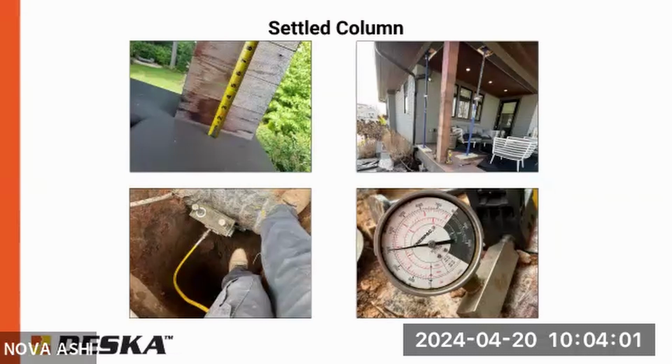And in the ground, there's not a lot of air. If you drive by a bridge and you see where the water line meets the bridge, and it's getting wet, and then it's drying, it's oxidizing, it's wet, dry. That's typically going to deteriorate much faster than something that's deep in the ground. If you look at a lot of the bridges in this area, they'll run piles with no galvanization at all, just raw steel piles in the ground. And I believe most of those designs are at least 75 years. So oxidization requires oxygen, and there's not much oxygen below grade. Yep.